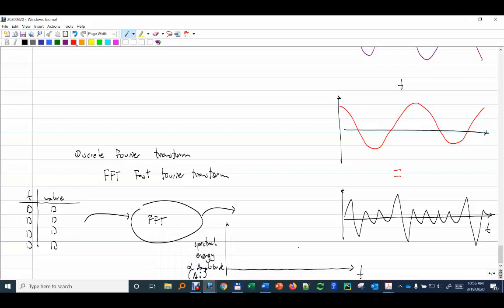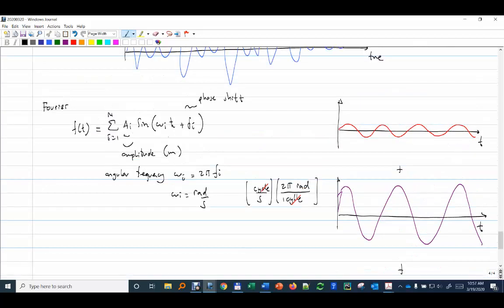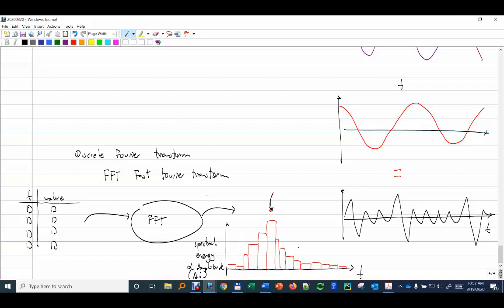Essentially, typically what we get is very few components, almost zero maybe for high frequencies and low frequencies, but then for one particular frequency range we start to have a big peak. That tells you there is a dominant frequency. Remember, the only thing the FFT is doing is calculating these A's and the omega, or the f, which is the same, for the whole range. When you apply the signal, it usually displays a peak, and that's what we call the spectral peak period.